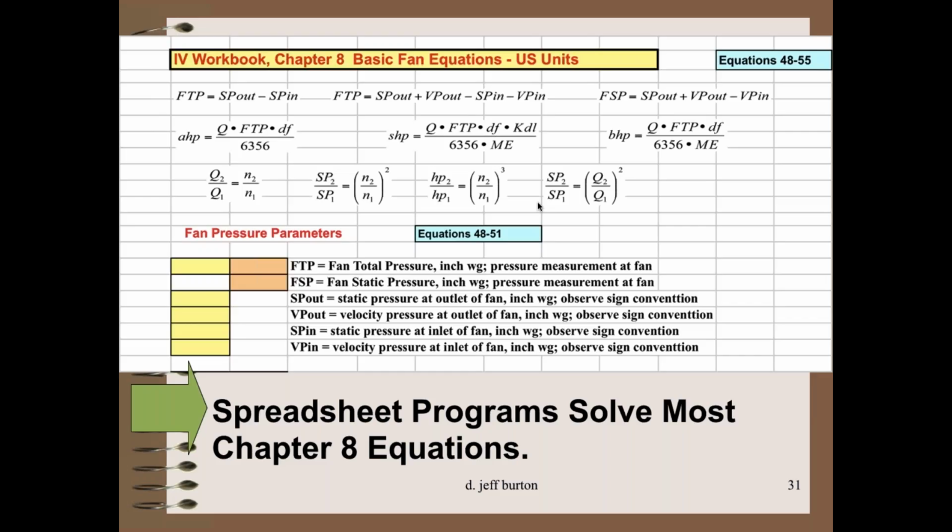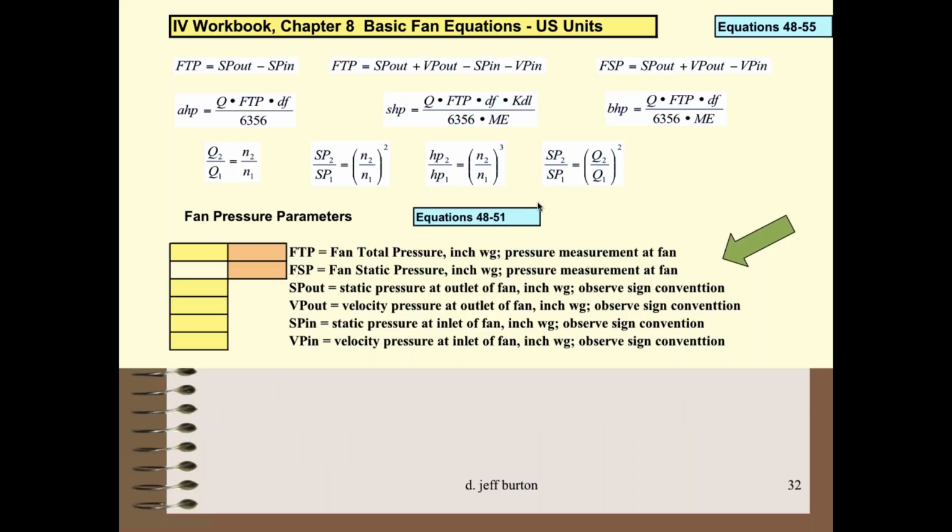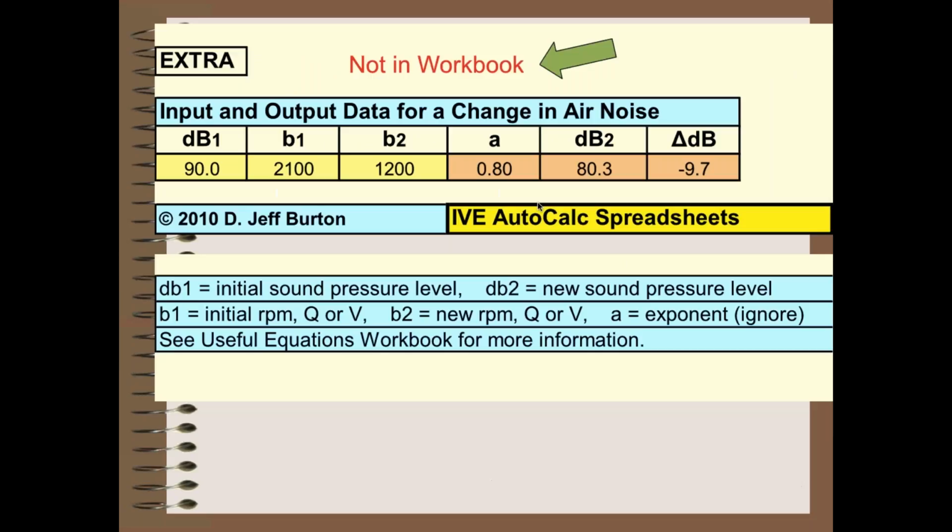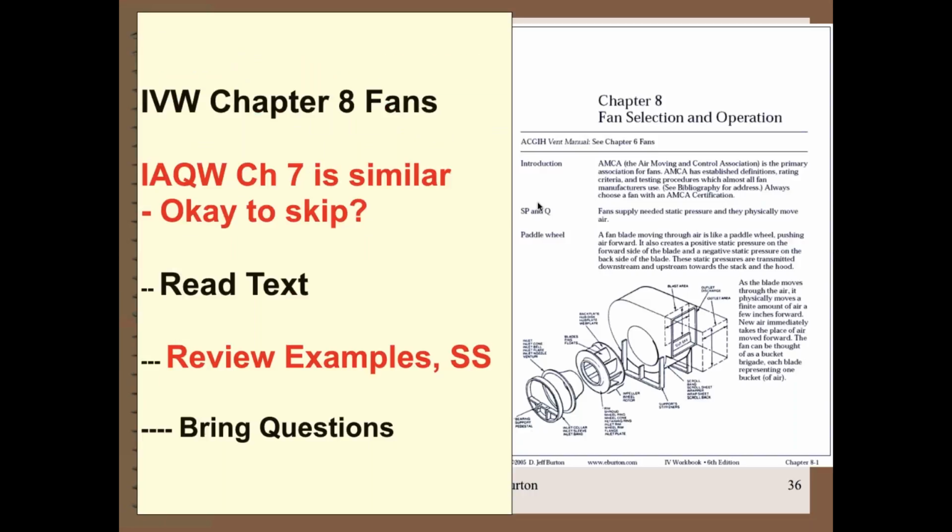Okay, watch alignments, of course. And why do we have that flexible material between the two of them? Because we want to isolate the vibrations and the noise. But is that doing anything? No, it's just like the ductwork. Yes, it's introducing a little bit of loss, but it's so short. It's only a couple of inches. In fact, a lot of times it may even be only a fraction of an inch that really separates the two ducts.